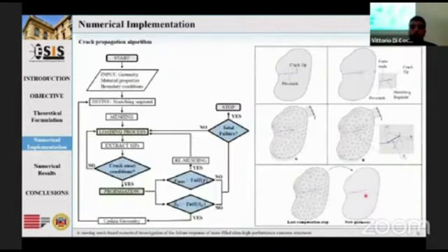The crack propagation mechanism is managed by an automatic algorithm. The analysis starts by defining geometry, mechanical properties, boundary conditions, and initial mesh configuration. During the simulation, the loads are slowly increased. For each increment, the stress intensity factors at the crack front are extracted and used to evaluate crack onset condition and direction of propagation. When this condition is fulfilled, the propagation occurs.